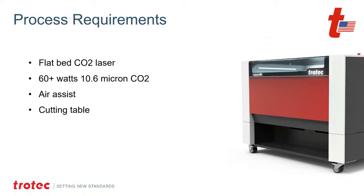It works mainly on a flatbed laser, 60 watt plus, 10.6 CO2 laser. Air assist and cutting table is recommended if you're going to engrave and cut it. If you're just engraving it, you don't necessarily need the cutting table, but if you're going to be doing both, which most do, then you would need those for processing this material.